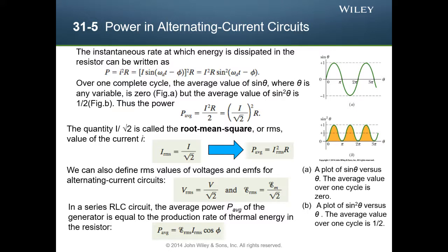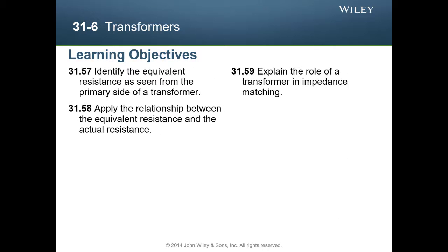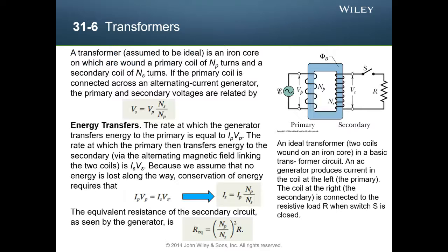And this is a root mean square. Root mean square means you take the square of it and then take the average and take the square root. So for a sine wave, it is nothing but dividing by the square root of 2. You can calculate the integration easily using the double angle equation.